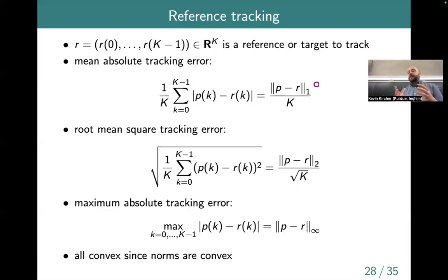So the idea would be, in order to regulate the frequency on the grid around that 60 hertz nominal operating point, we would have a bunch of resources. They could be power plants, like a gas power plant or a hydro plant, but they could also be a bunch of DERs, air conditioners, batteries, and things like that. And they would be constantly playing this game where they get a reference signal, an R, from the grid operator, and that would say, use more, use less. And then they would ramp up or down their consumption kind of in proportion.